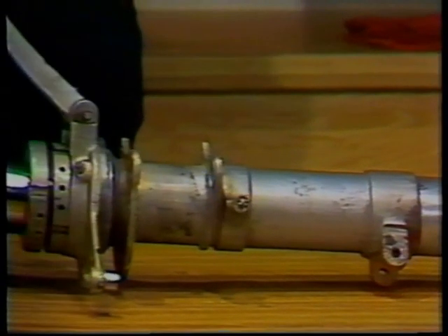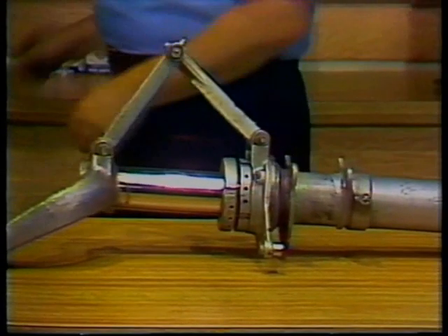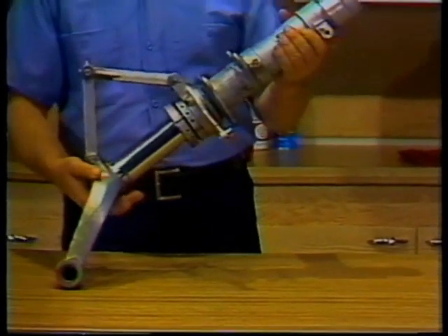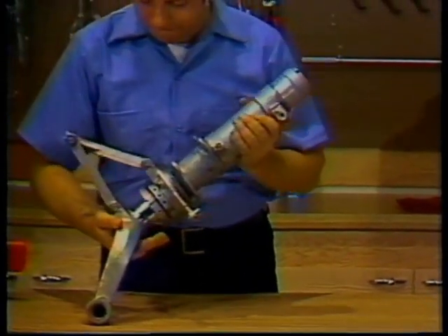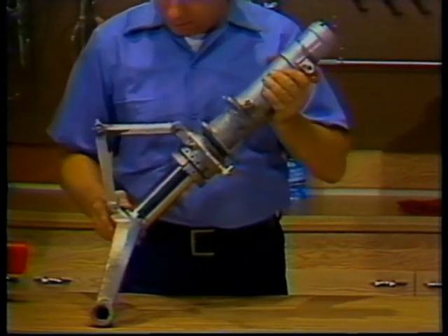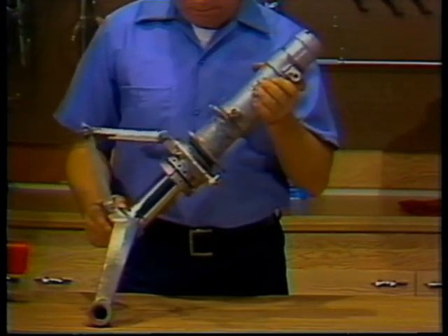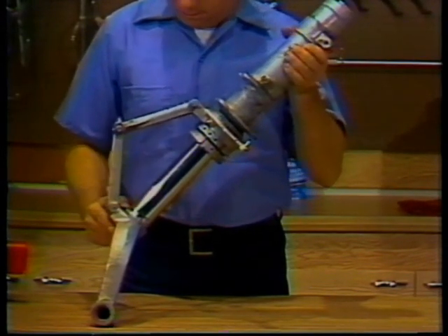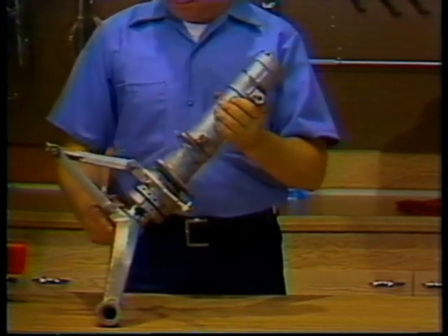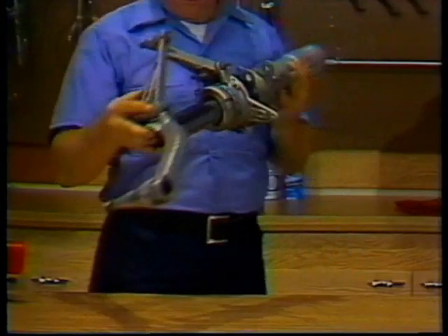A typical pneumatic hydraulic shock strut uses compressed air combined with hydraulic fluid to absorb and dissipate shock loads, and is commonly called the air oil or Oleo strut. The Oleo strut is made up of two tubes which telescope one inside the other. The tubes are closed on the outer ends.